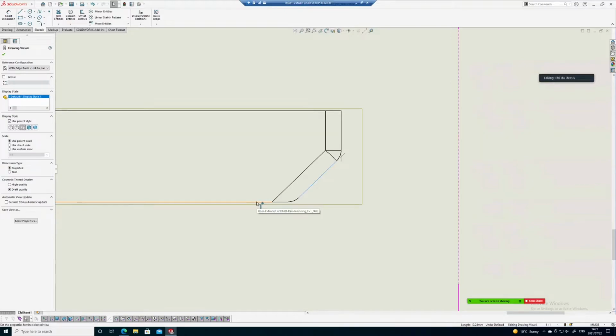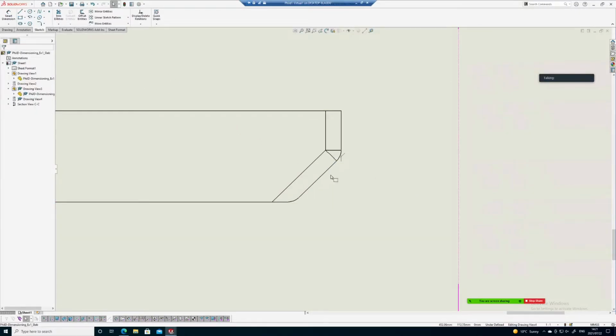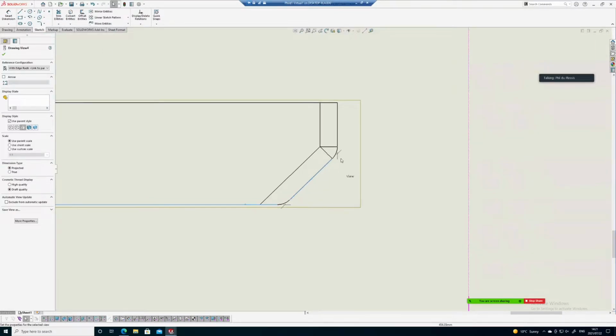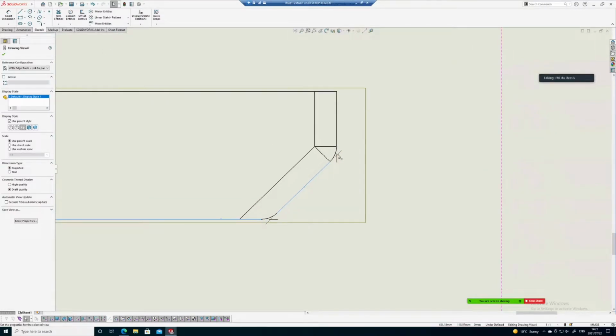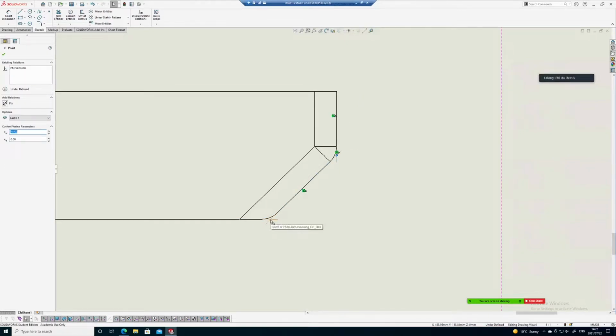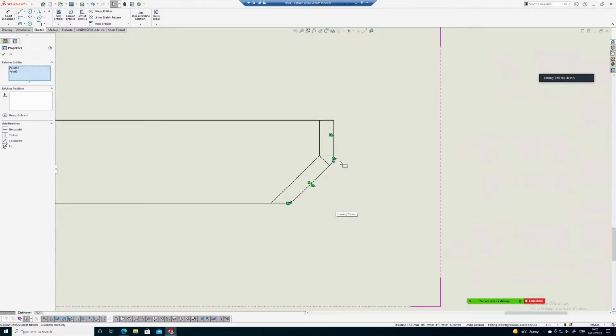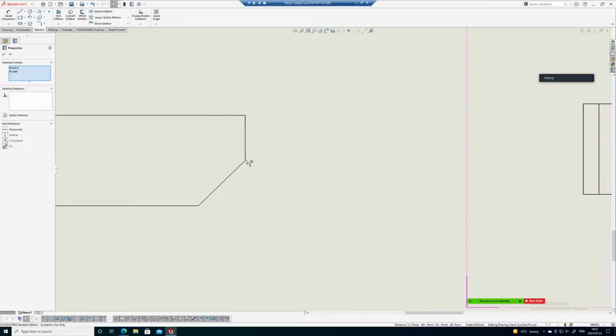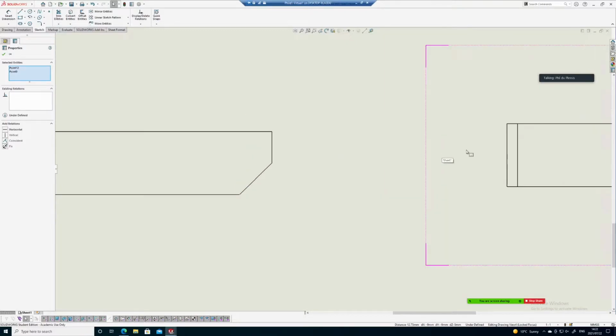So I'm going to select, shift select. Let's try that again, because maybe it's control select as well. Never can remember. Yeah, it's control select or shift select. Alright, so there my two virtual sharps are. Now, if you think about it, these two little points, coordinates, are the same as these two points here, before we put the radii in.